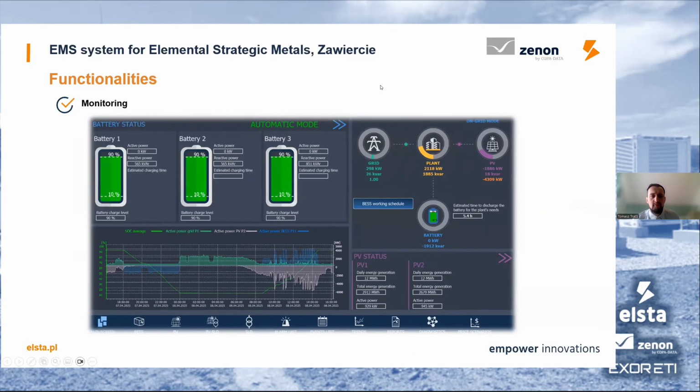The general overview is also presented. As you can see, you get the charging of the storage flowing through the process. These graphs are updated, I think, every minute. As you can see, we also introduced 10 and 90% limits to keep the batteries, let's say, in optimal condition, so they can last more charges.